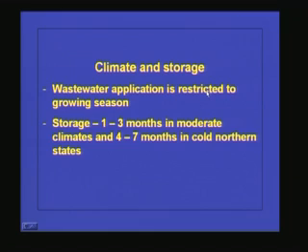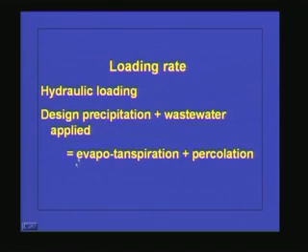Wastewater application is restricted only to the growing season, because only then can the plants utilize the nutrients. Storage of 1 to 3 months is required in moderate climates, and 4 to 7 months in cold climates. The loading rate we have already seen, and the hydraulic loading rate should be such that the design precipitation plus wastewater applied should be equal to the evapotranspiration plus percolation. This is very, very important.